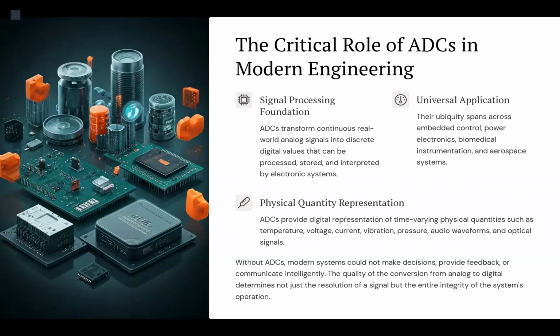Now, the DC testing, which we call static performance characterization, and we're going to discuss that later on, emphasizes that the primary concern is how accurately the ADC responds to the DC inputs. We have key parameters on that, like offset error, gain error, and INL and DNL, which we are going to go through, and we are going to have a case study over them.